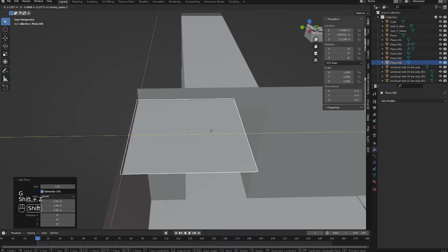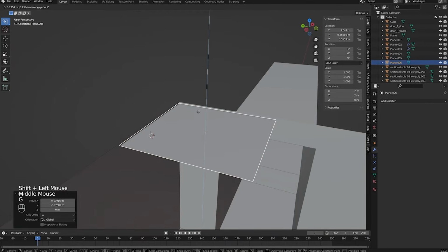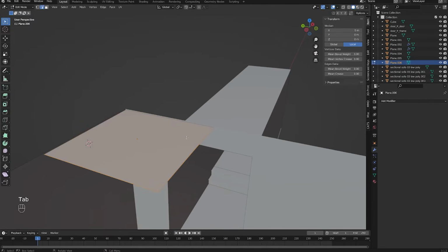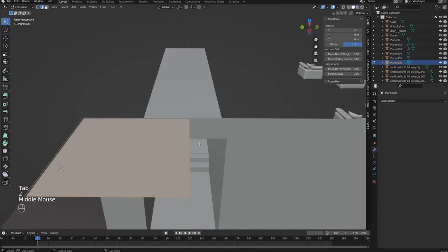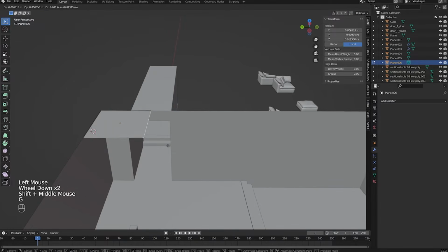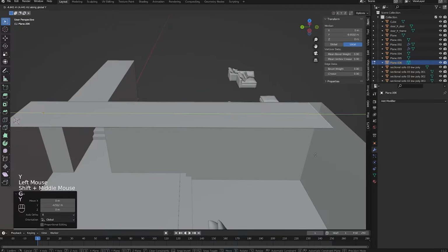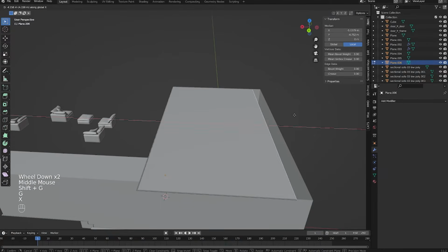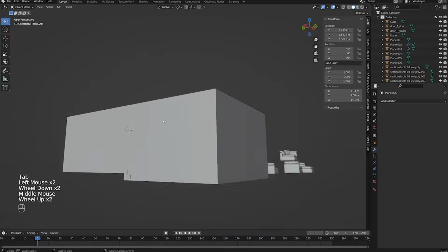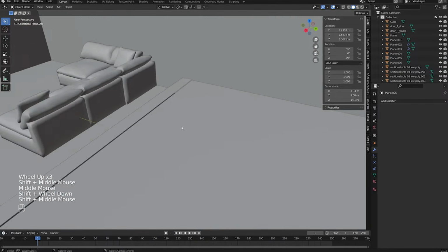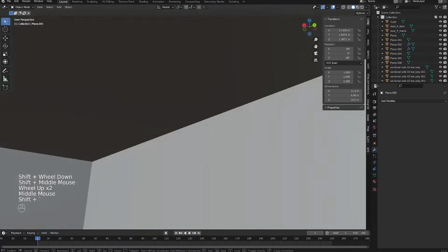and we can take this plane and just kind of move it around, place it where we want it, press G to move it, Z to lock to the Z axis, pressing Tab, let's press 2 to go to the edge select this edge, G to move, Y to lock it to the Y axis, do the same thing, but this G to move, X to the X axis, and now this is a very much enclosed room. Have we done it? It's basically done. We did it. A room.